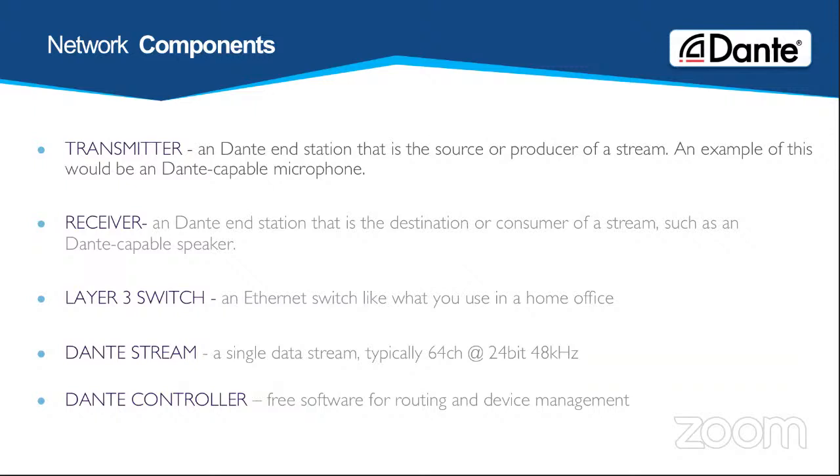It's Dante. You can buy a microphone. It's Dante. It's one audio channel. But normally when you get to the central portion of your Dante network, where you're dealing with a DSP device or a mixer or some central distribution point, each chipset, each Cat5 port basically is a Brooklyn 2 chip typically. And that would give you 64 channels at 48K, 32 channels at 96K, and 16 channels at 192.